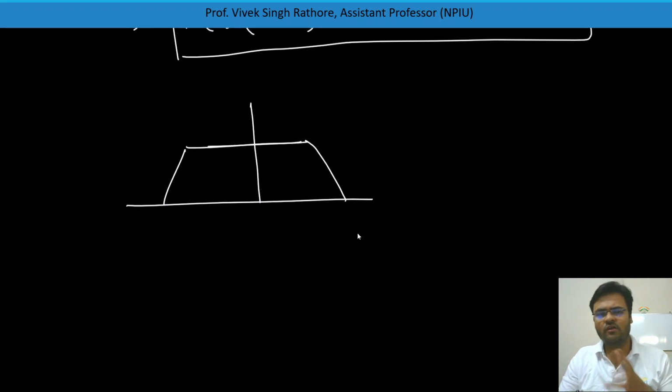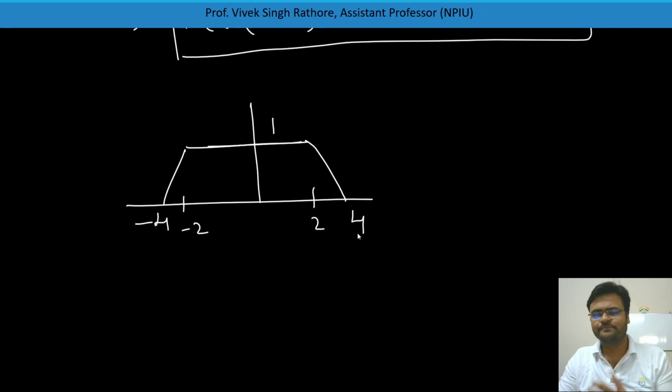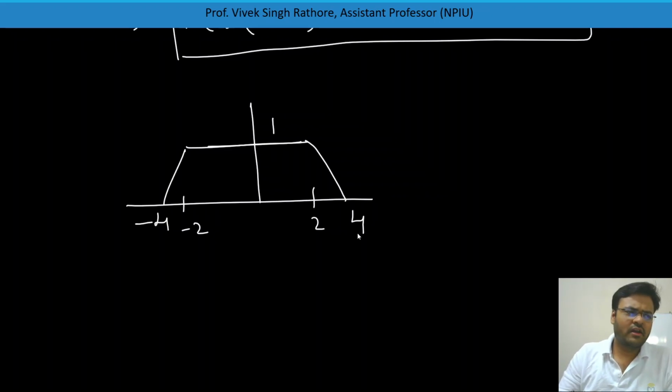So many signals are possible. If I give you a trapezoidal signal, there is a mixture of signals. Here the trapezoidal signal has points at -4, -2, 2 and 4, and let's suppose the magnitude is 4 only. This trapezoidal signal consists of unit ramps and DC values also. Let's see how we can plot it.